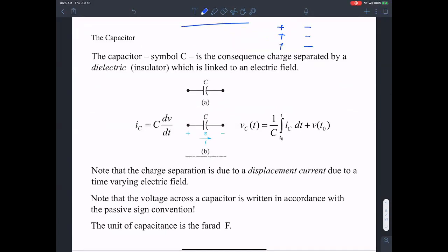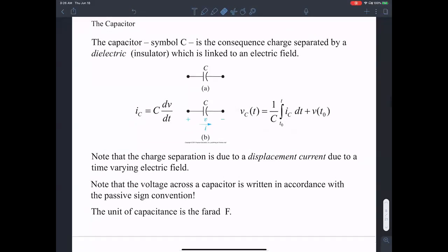So if you have an electric wire carrying current in the north, and right below it is another charge carrying conductor, and there is some air in between them, some dielectric, some insulator between them, inadvertently, even without you making an effort to create a capacitance, that automatically leads to some kind of capacitance. Okay, so you'll see this come up in places that you least expect. So the idea is when charges are separated by an insulator, that leads to a capacitance.